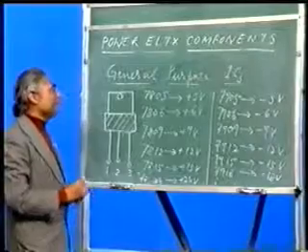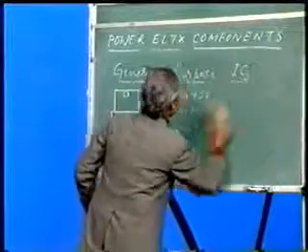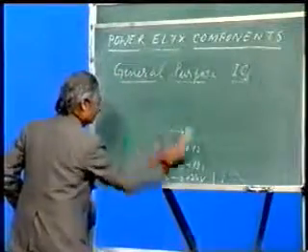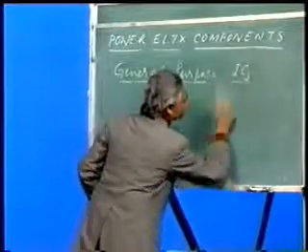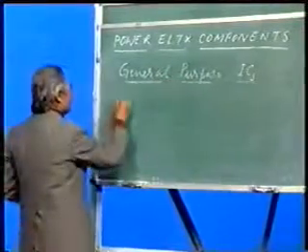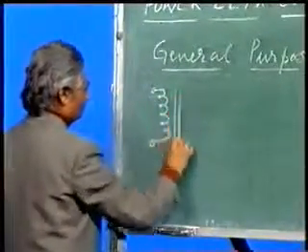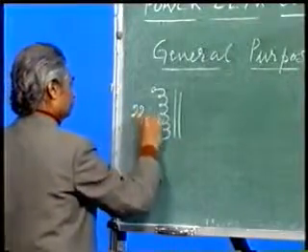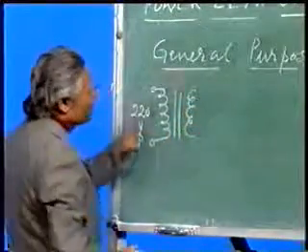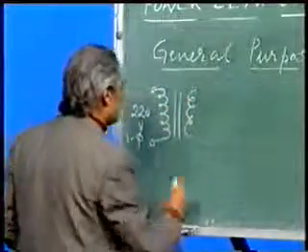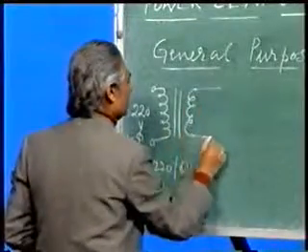So how do you generate it? There could be a very simple circuit. I will try to explain it. You see, I will have a transformer first, which has to be a step down because this is 220 volt here, single phase. Output will depend how much you need. Suppose we need a 6 volt supply, so it has to be 6 volt. That means 220/6 volt.